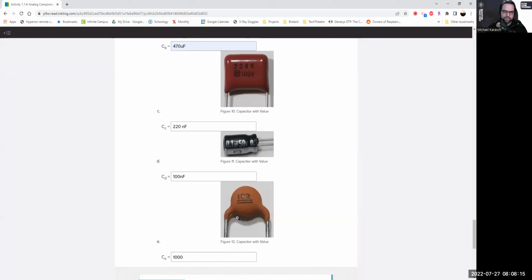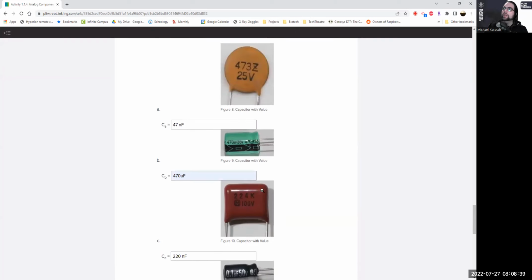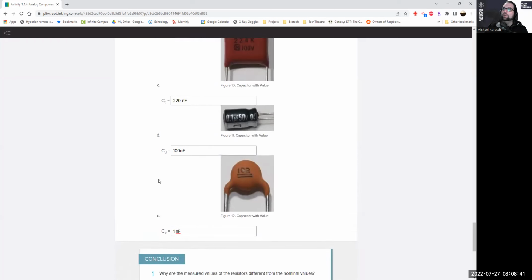And because it's a disc capacitor, that's in picofarads. Now, technically, that's not engineering notation because I have 4 numbers here. So I'm going to go back 3 decimal places. 1, 2, 3. And that would be in nanofarad. For better or worse, almost every answer here is in nanofarad. That's just coincidental, how that worked out. Thanks for asking, Tyler.